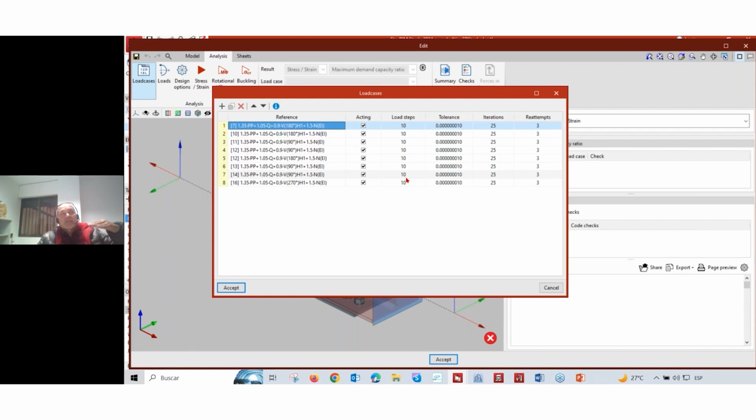That means the first analysis is going to start with 20 tons, and then it does the complete analysis, goes back, upgrades to 40 tons, then 60 tons, 80 tons, up to the end. Perhaps the solution is going to be less than 100 tons, but the software does the entire process.